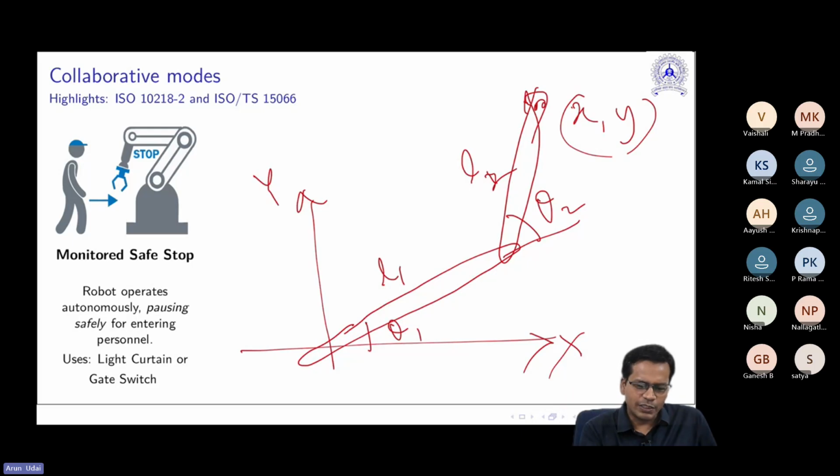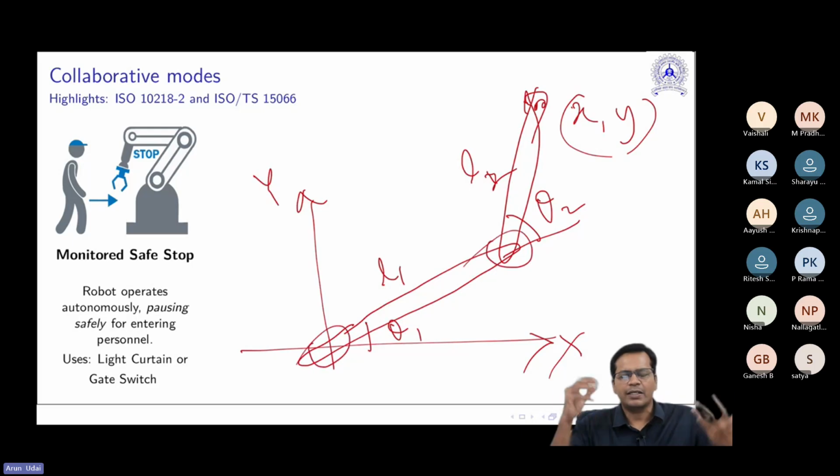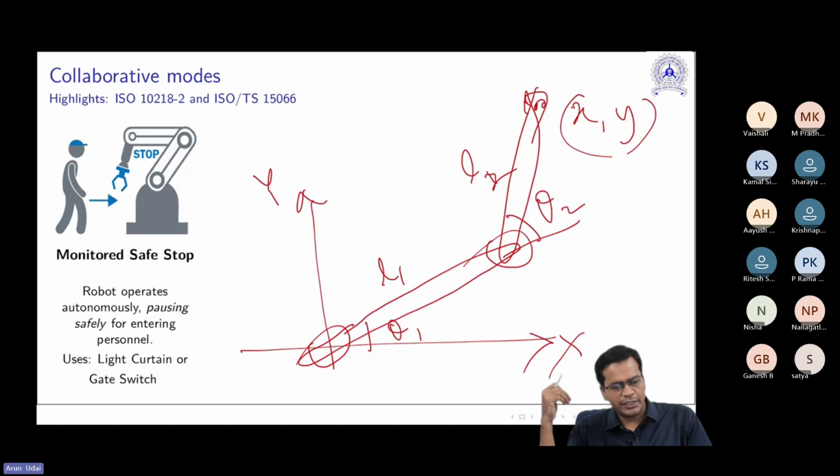If you can control the joint angle, if you just buy a typical geared DC motor with encoder, available anywhere, on Robu or Amazon or anywhere, take this and make one. Who is stopping you? And then to make it a torque controller, you use any chopper drive. Now you are using an H bridge drive. You can use any chopper drive, you can make it. So commercially we have failed. Technologically we haven't. We know it in and out.